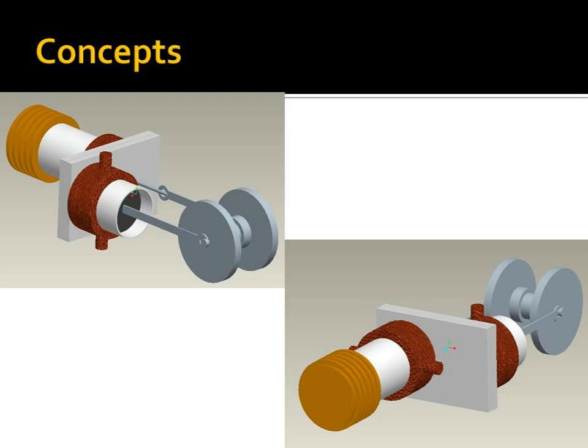We're looking at balsa wood as a displacer piston, though it's considered a hardwood. It is very soft, so it wouldn't actually be able to be hollowed out. You can actually carve balsa wood with a knife. It's that soft, though it's considered a hardwood. And it would also mean sealing the wood to protect it from the high temperatures experienced within the engine. The engine, by the way, will be operating at 755 Kelvin, which is about 600 degrees C, or 900 degrees Fahrenheit for the Americans.